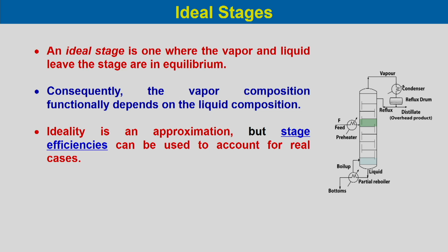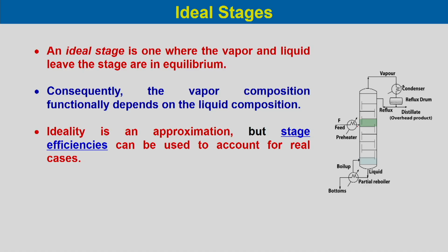As we said earlier, for any tray there is a liquid level maintained and the vapor from the bottom goes through the perforations of the plates, and there are different plate designs we have already discussed. It flows through the liquid and there is intimate mixing between the gas and liquid on that liquid pool, and after that it disengages from the liquid and goes to the next stage.